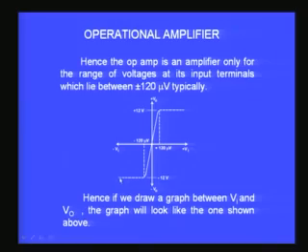You can use the amplifier in other applications where it is not the amplifying action which is going to be useful to us in different circuits, but this characteristic that it is able to distinguish between two voltages which are varying at the two input terminals within plus or minus 120 microvolt, then the output shows a sudden variation from anywhere between minus 12 volts to plus 12 volts or whatever, and therefore this switching at the output will be very useful for applications where the operational amplifier will not be a simple linear device, but it will become a non-linear device, and basically it is called a comparator.